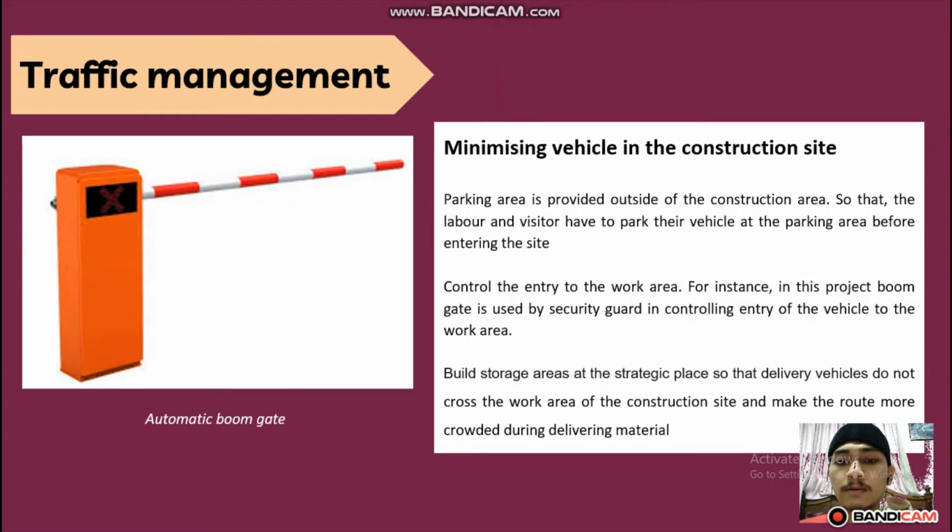Secondly, controlling the entry of the work area. For instance, in this project, a boom gate is used by a security guard in controlling entry of vehicles to the work area. Lastly, build a storage area at a strategic place so that delivery vehicles do not cross the work area of the construction site and make the road more crowded during delivering material.